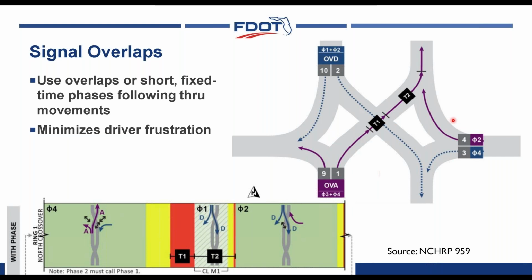And then the same principle could be applied at the end of the southbound through movement by releasing the northbound movement slightly earlier. So while this is only going to gain you maybe 3 seconds a cycle, which doesn't necessarily seem like a lot, over the course of an hour, this can add up to a minute or more of additional green time that you've given both directions of the major street, which can reduce the queuing and also keep the space between the crossovers hopefully clear of vehicles.